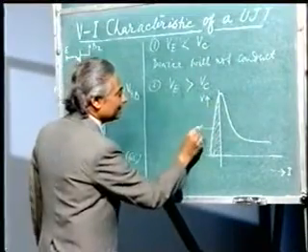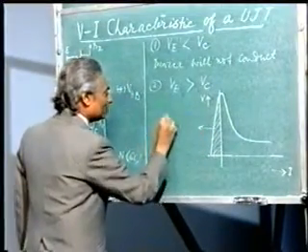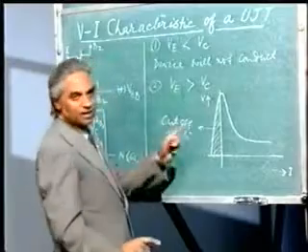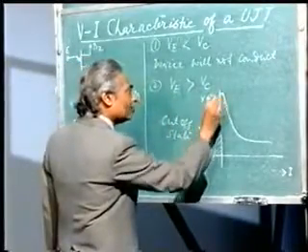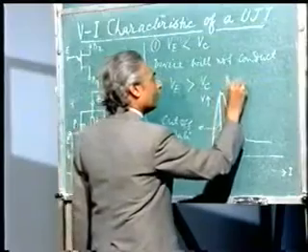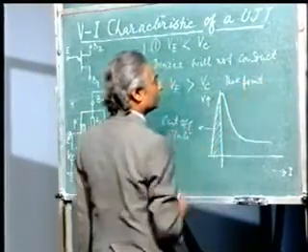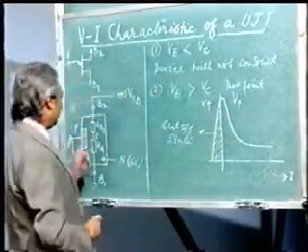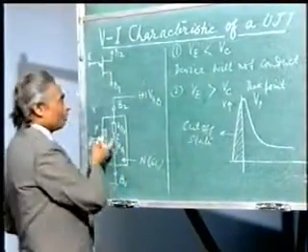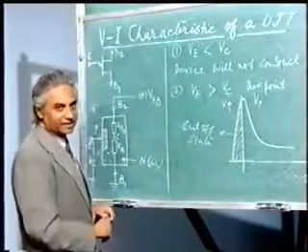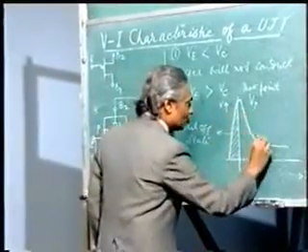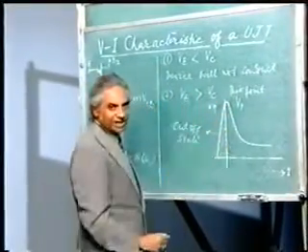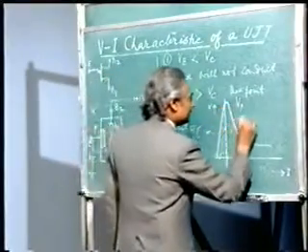This is known as cutoff state, where there is no conduction of the device. Now at this point, which is known as peak point, the corresponding voltage is Vp, which is peak point voltage. Suddenly the diode becomes forward biased, that is VE is greater than VC, and it starts conducting. From this position to this position, it starts conducting. But what you are seeing here, the voltage is reduced, the current is increased. So from here to here it is the